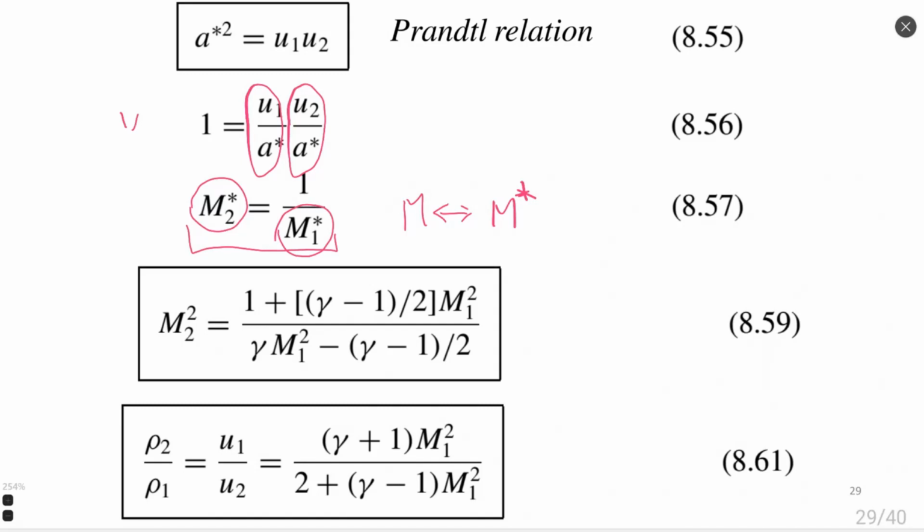We obtain, in the usual Mach number, a function relating velocities before and after the shock wave. We can see this is a function of Mach number, right, and just a function of gamma. There is no other parameter that influences this relation. So we use this relation.